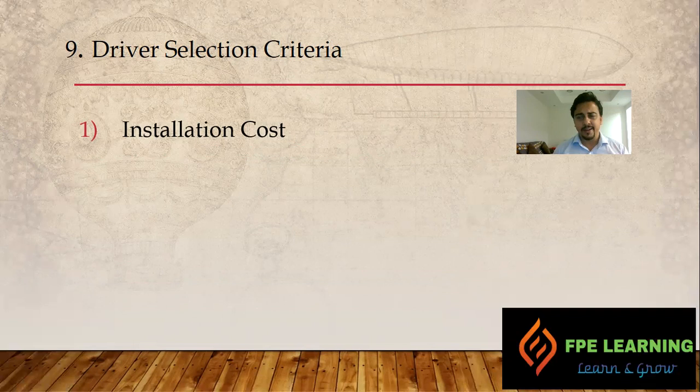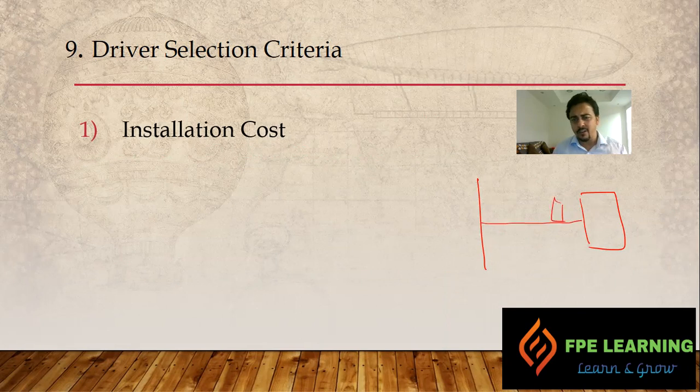Let's compare diesel engine and electricity. In some countries, if the electricity cost is very high, the charge of electricity is very high, of course they will go with the diesel engine, because the cost of the fuel is much lower than the electricity. The second option, if at the installation site there is no electricity, it is not reliable to bring electricity all the way from far with a transformer for this facility. So you have to go with the diesel pump. If you would have to buy a transformer for that, then it is better to go with the diesel pump.